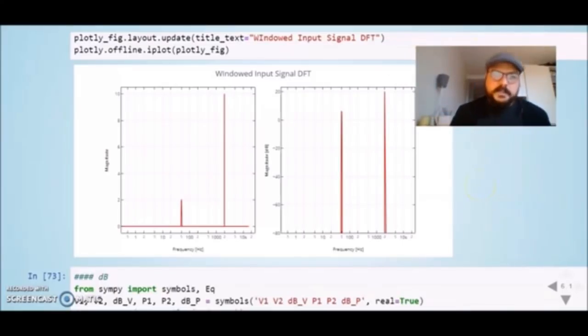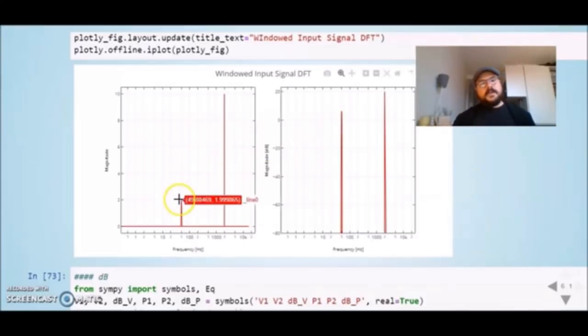And now we come to the dB scale. So we will take a reference of 1 volt. So we had an amplitude of 2 volts. In the dB scale, it will be represented by 6 dB. If we have 10 volts in the dB scale with a reference of 1 volt, we have 20 dB. So we can already see that there is a ratio of 2: 2 volts and our reference voltage is 1, so we get 6 dB. And when we have 10 volts and the reference voltage is 1 volt, we have 20 dB.